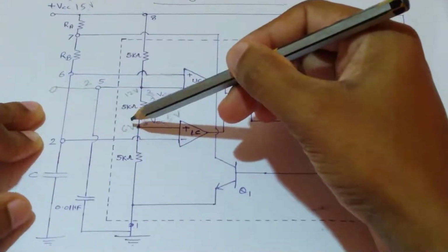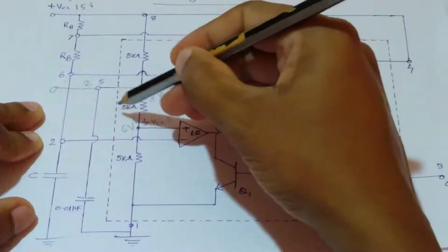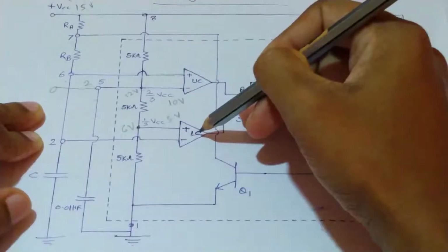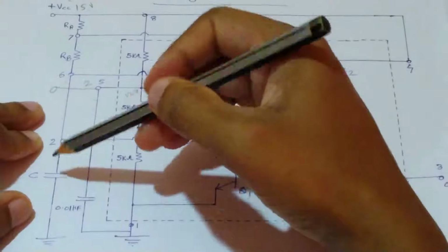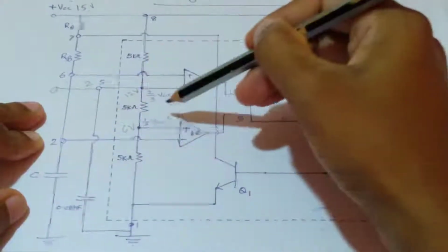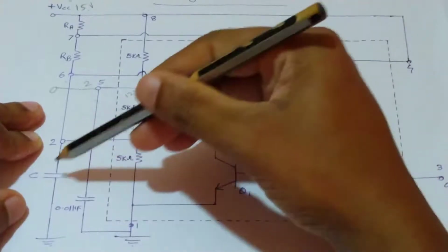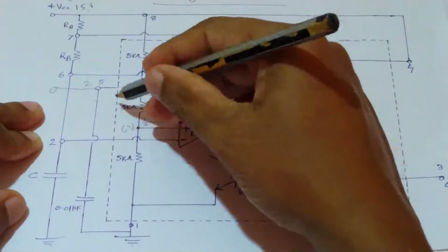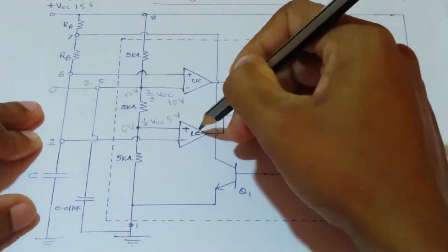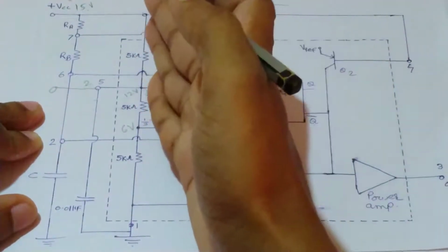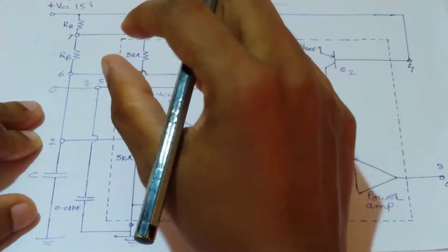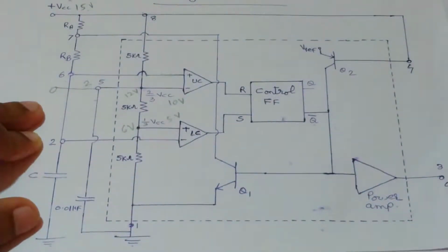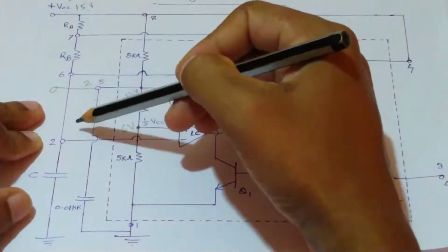So when the voltage across the capacitor goes below that 6 volt, this lower comparator triggers. Hence the lower comparator triggers early in this case, because there is no need for the voltage across this capacitor to go below the 5 volt. When the voltage across the capacitor goes below the 6 volt, the lower comparator gets triggered. So that lower comparator will trigger early, and hence the duration in which the output remains in its low state gets reduced. Hence the time duration in which the output remains in its low state is reduced when the voltage at the fifth pin goes on increasing.